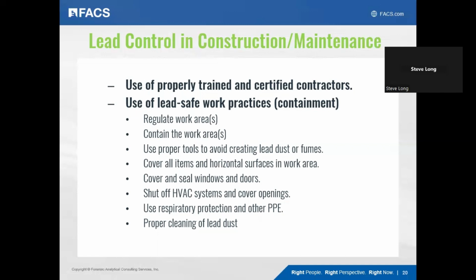And finally, the last step of a job that's going to be disturbing lead paint is going to be cleaning up lead dust so that nothing residual is being left behind. So even after the pulling up of the plastic that's been covering surfaces, cleaning the surfaces underneath to be absolutely sure that we're meeting those lead hazard numbers and not leaving behind a lead hazard after the work.